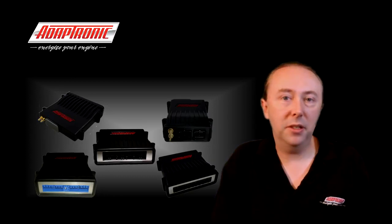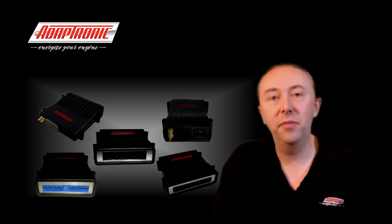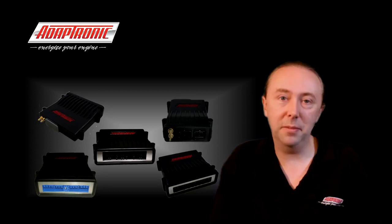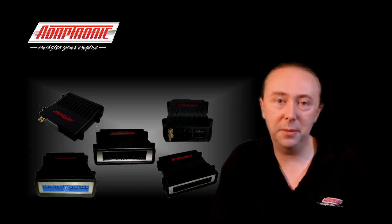Now, if you expand a modular ECU with one of the mini aux output modules, then you get 6 push-pull auxiliary outputs, so they can provide power or provide the ground side switch. They can all be pulse width modulated, and you can use them for pretty much whatever you like.